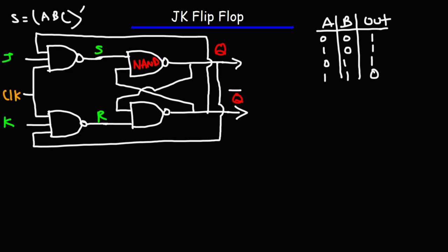So that's what we're going to do right now. We're going to have an active clock input, and then we're going to press the K button. That's going to set Q to 0 and Q bar to 1. So that's going to be our starting values. Now we're going to create a truth table for this circuit. So let's see if I can fit that here.